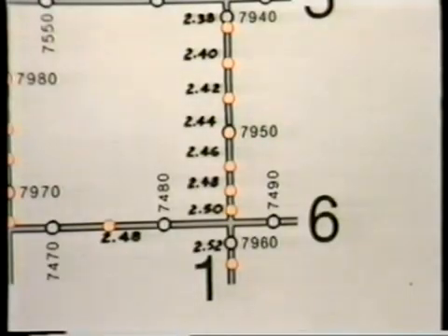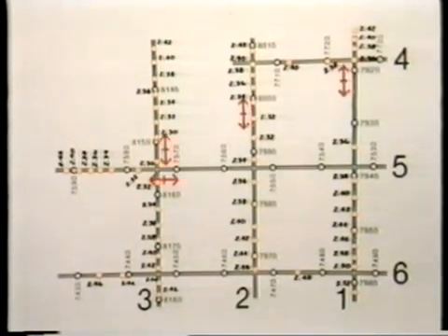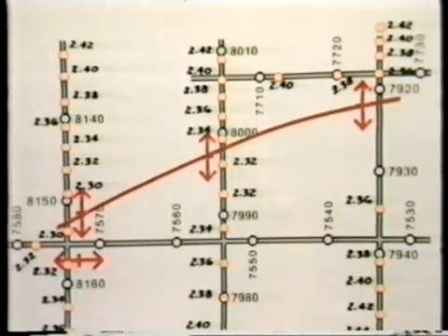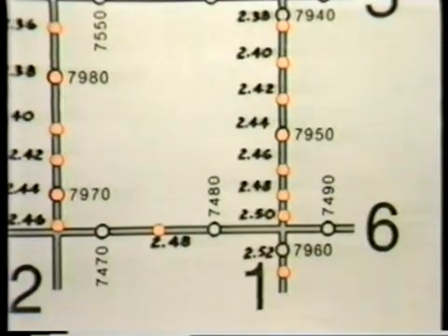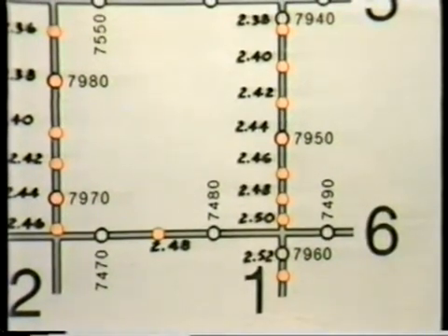But eventually, when the timing and the posting are done, we can start the contouring, and that's much more fun. First, we look for the trends. In this case, we check the axis of our high, those two-way dip symbols we put on earlier. So the axis is this way. Then, with that as a guide, we look for a simple place to start drawing the contours. There. That'll do nicely. Just rough them in at first.